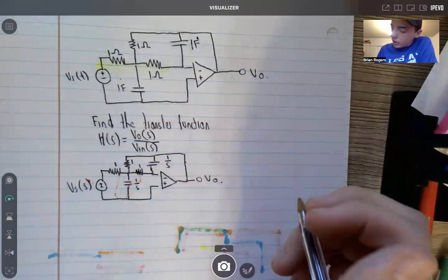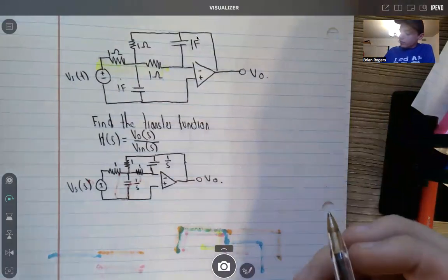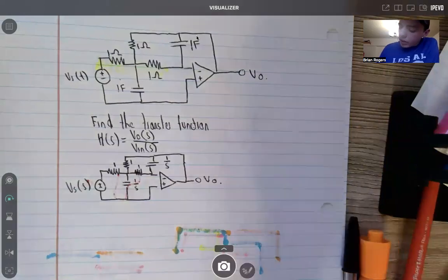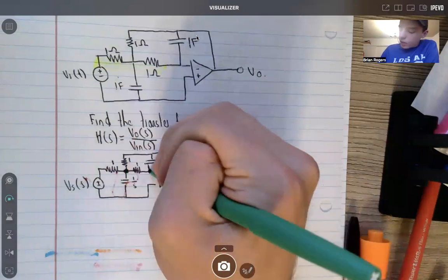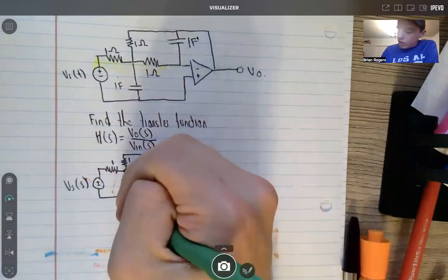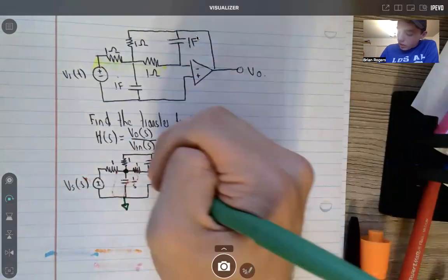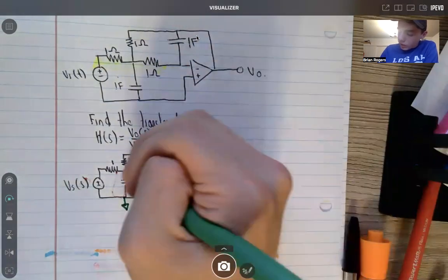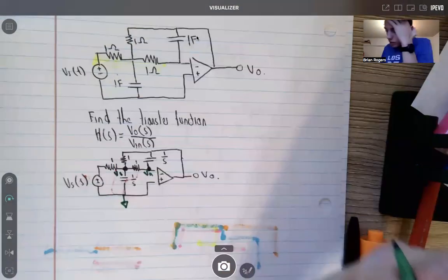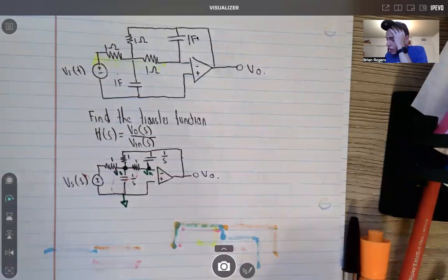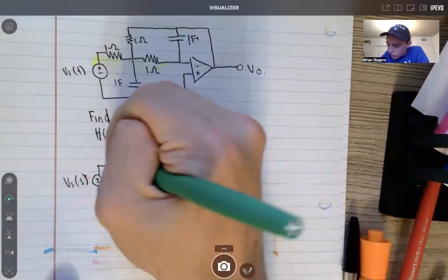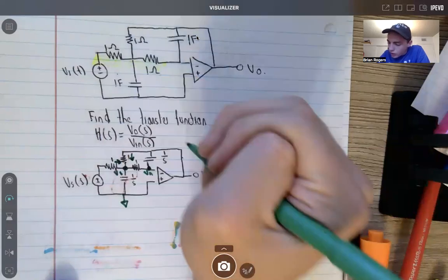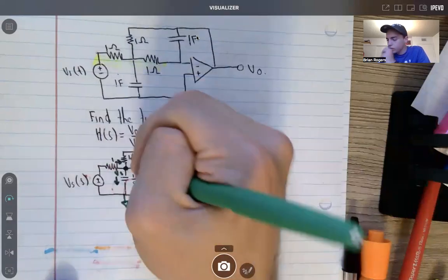We know if we're doing our circuit analysis, remember you define the essential nodes, which are connected to 3 or more elements. And you make one ground. And so this is our V of N here. This is our V1, I'll call it. And so what I'm going to do now is draw currents basically going into each of these. So here, this current would be going in to this node. This one would be coming back out. This one would be going downwards, and this one would be going to the right or something like that.